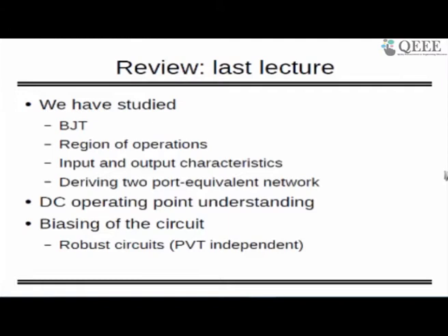When I say process dependent, it means your circuit should not give you a wrong or unexpected answer when the transistor is changing. It should not depend on the manufacturing quality of the BJT. We know that BJT's beta varies from 50 to 200, or it may be more than that, sometimes lesser, but still my circuit should give me the desired answer.